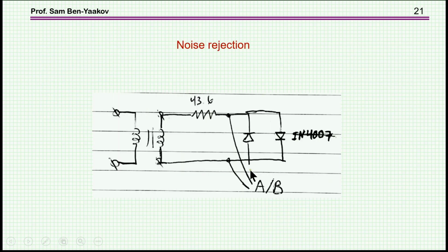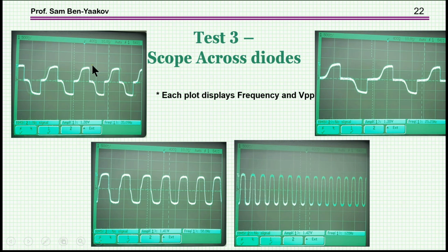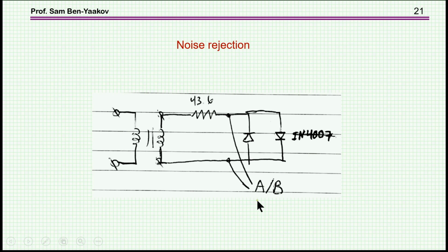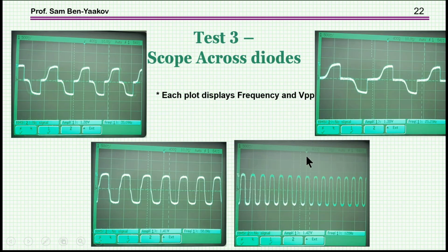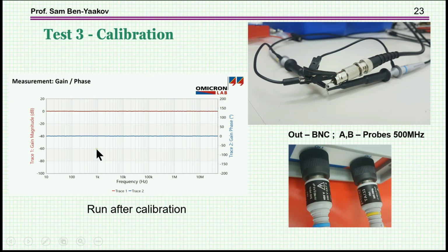And so the analyzer has to be able to look at the sinusoidal first harmonic of the excitation, or the excitation itself, very accurately in amplitude and phase, extract it from here, and be able to give us the value, because when we look at A over B, this is for the particular frequency injected at this particular moment. But before doing that, we'll do a calibration.